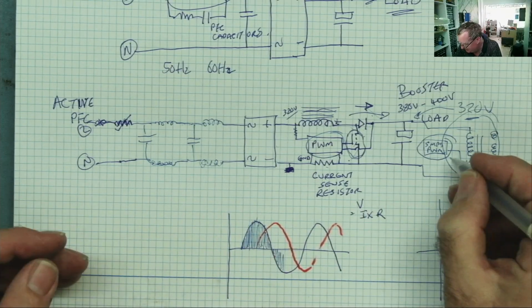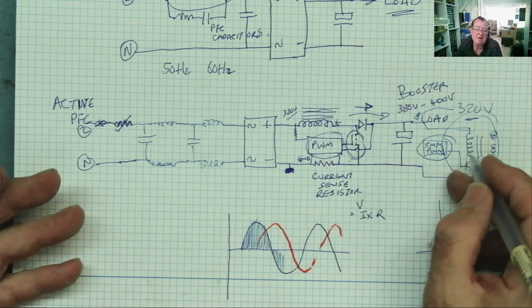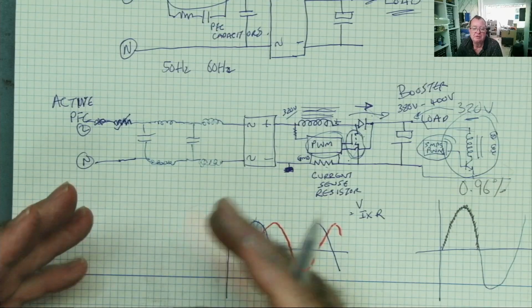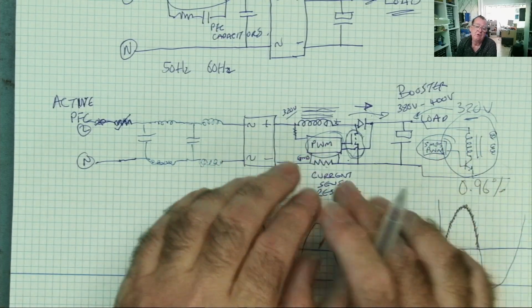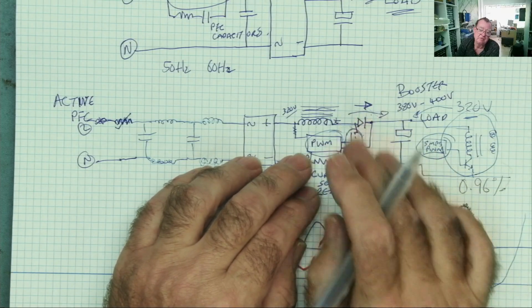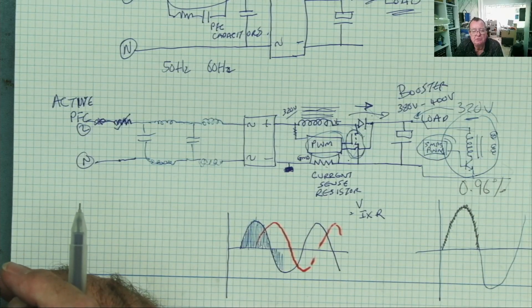Easiest way to figure this out, to be quite honest, is to find the controller for either, look up the data sheet, and you'll know straight away if this is a combined controller like this, or we have a separate pulse width modulator for the PFC and a pulse width modulator for the power supply. So that's another thing you should just keep in mind.